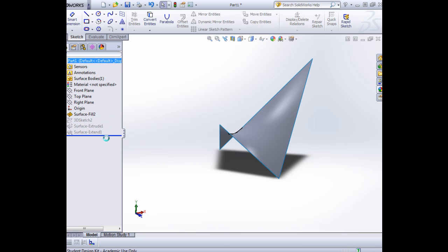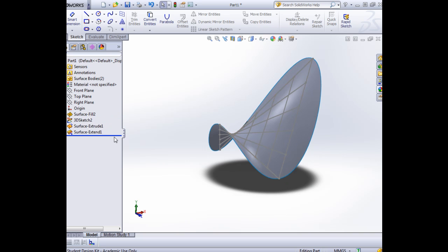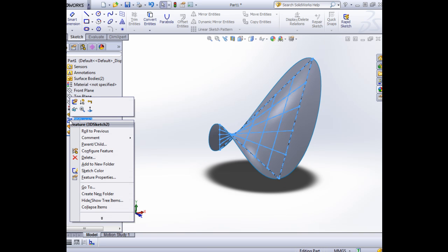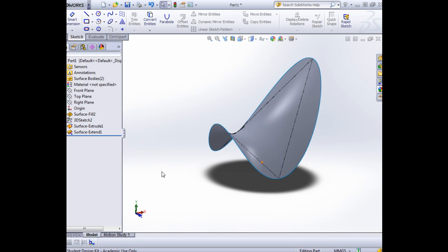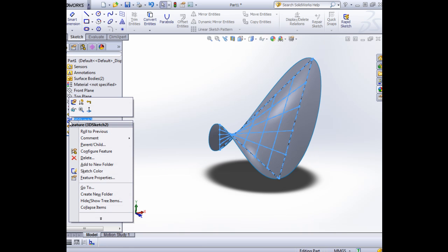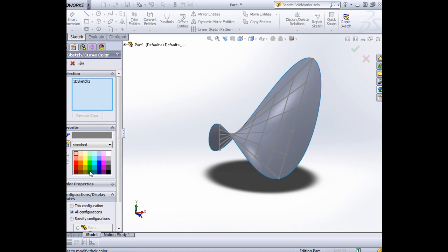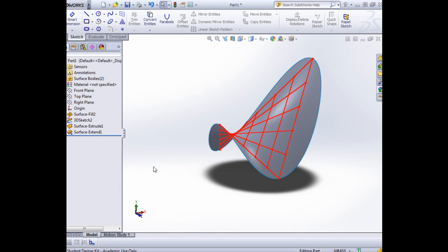These guys here? Yeah. You can, of course. You can hide anything at any stage. If you go over here and right click and just hit the glasses, it'll hide them like that. So right click again, hit the glasses again, and it'll bring them back. You can also change the colour of them, because obviously enough grey, they don't look great there like that. You can change the colour of them by, is it sketch colour? That sounds right. Yeah. So that'll be your sketch colour like that.